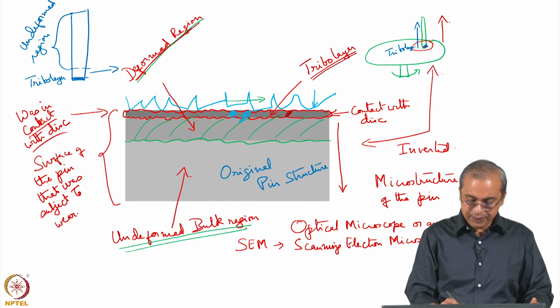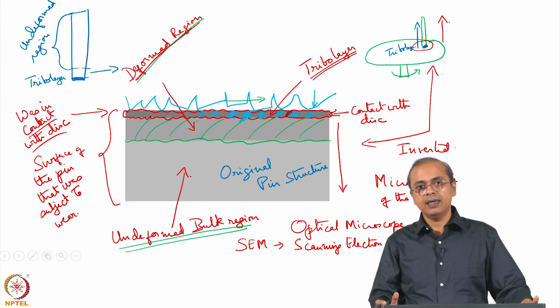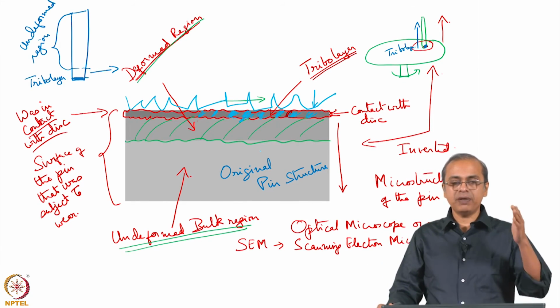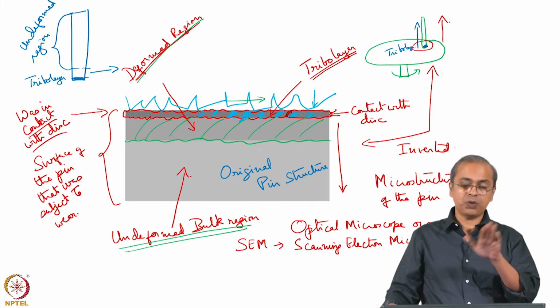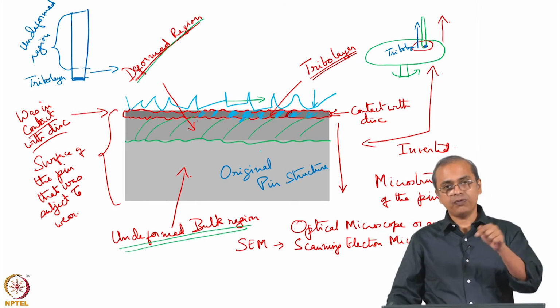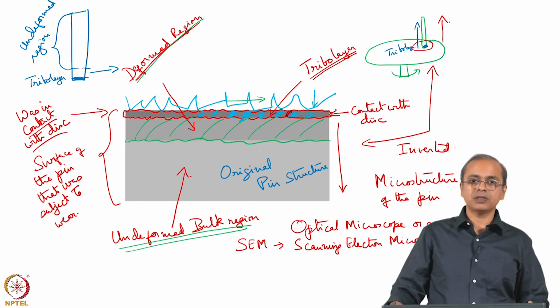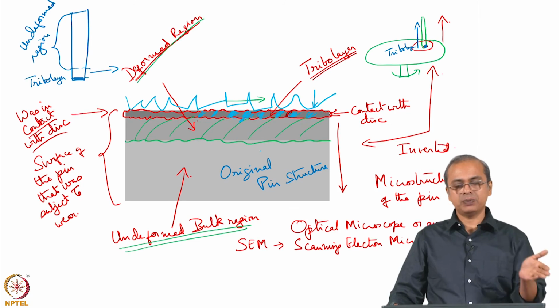But in addition, the debris that has been formed due to the wear is also participating and assisting this wear process. So, like I said, if you have an oxide layer and that oxide layer is protective, then it is helpful, but if the oxide layer breaks down and also forms a hard particle that can impact the degradation process, then it is not helpful, it actually makes the situation worse.